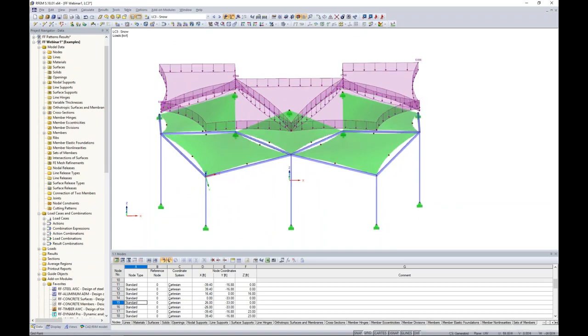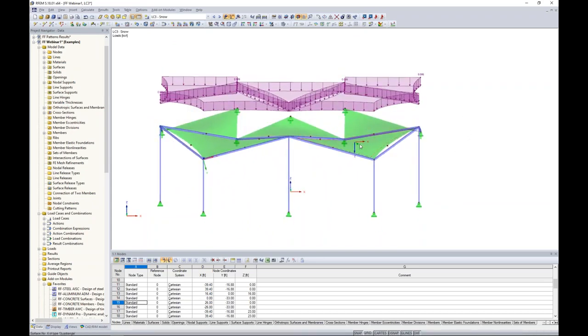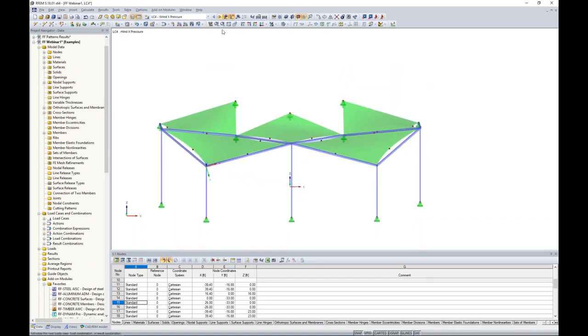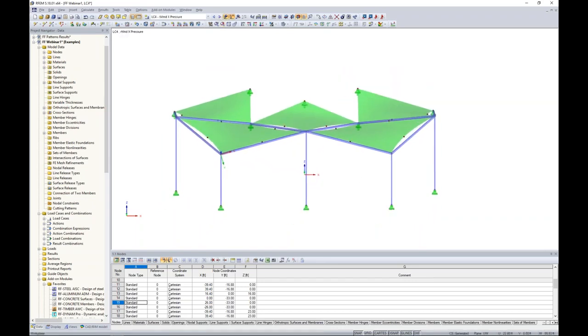The program will account for those angles, but at these areas where our membranes are relatively flat, we're going to see higher snow loads there. So that's the advantage of a projected load. When it comes to our wind loads, according to the ASCE 7, Table 30.11-1, this does address wind loads on attached canopies. So for time's sake, we don't have time to get into this today,